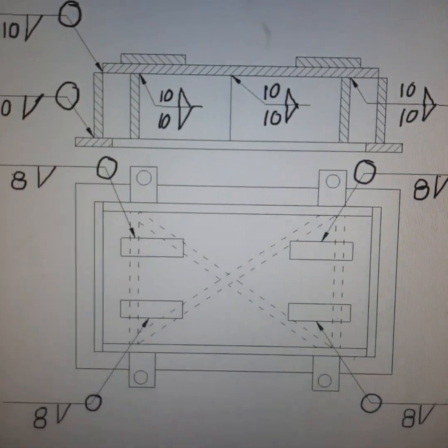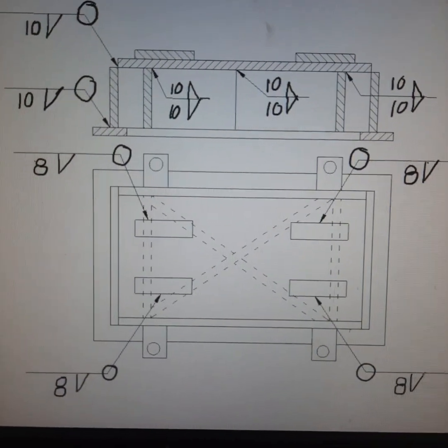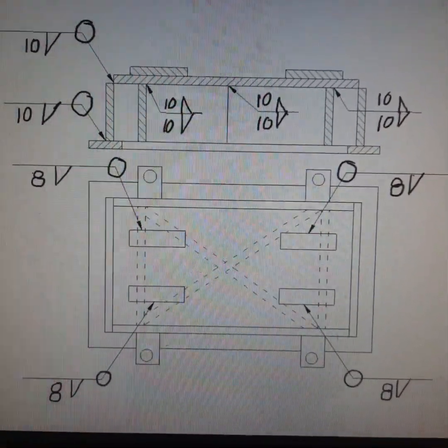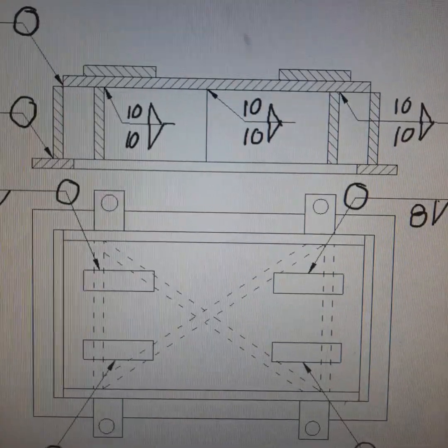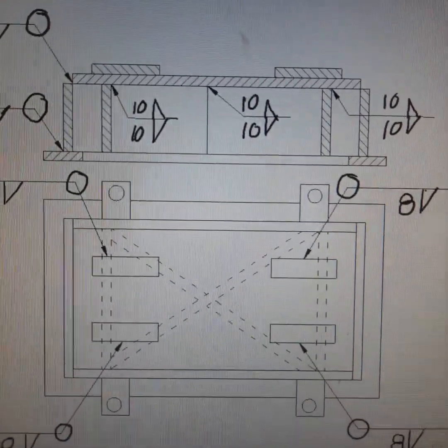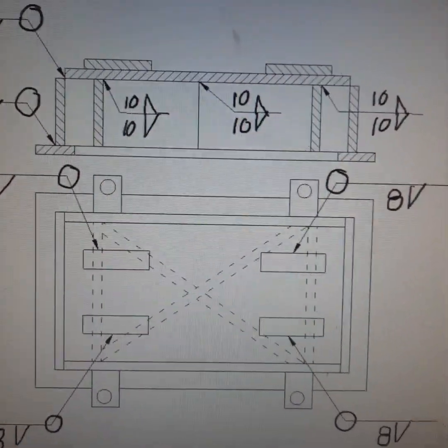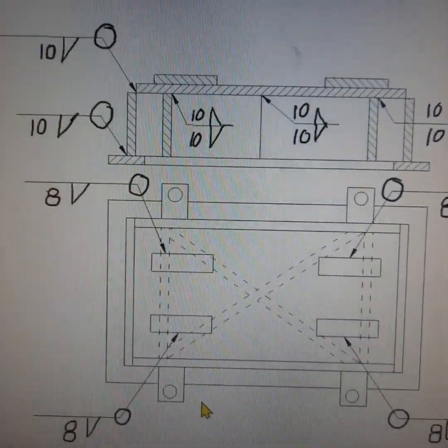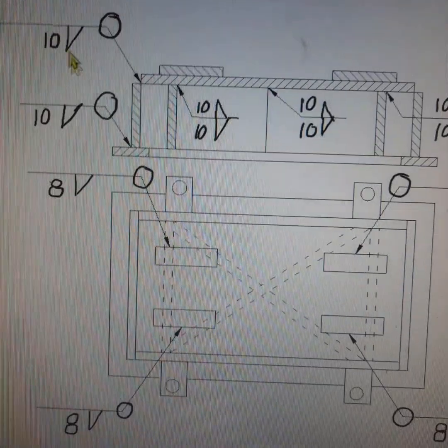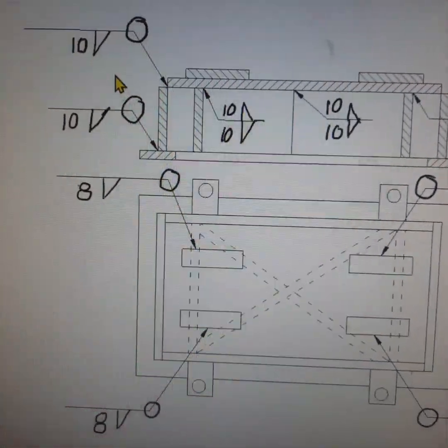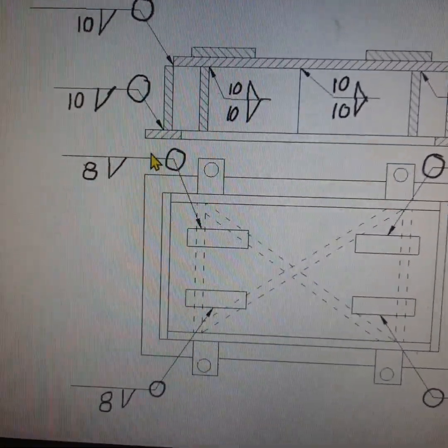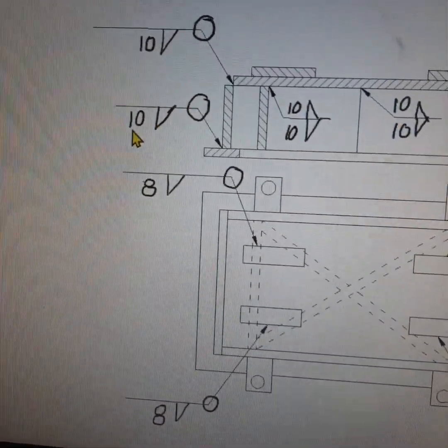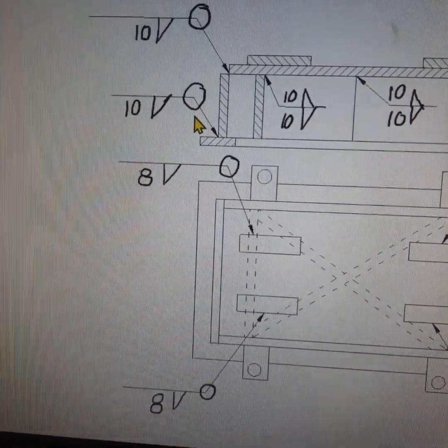Now this is the machine tool bed fabricated using welding. We have drawn the orthographic view of the machine tool bed, sectional elevation and top view. Over this drawing we have added the welding symbols. For example, we have 4 vertical plates joined to the base using a fillet weld of size 10 mm. It is to be done on all the 4 sides.